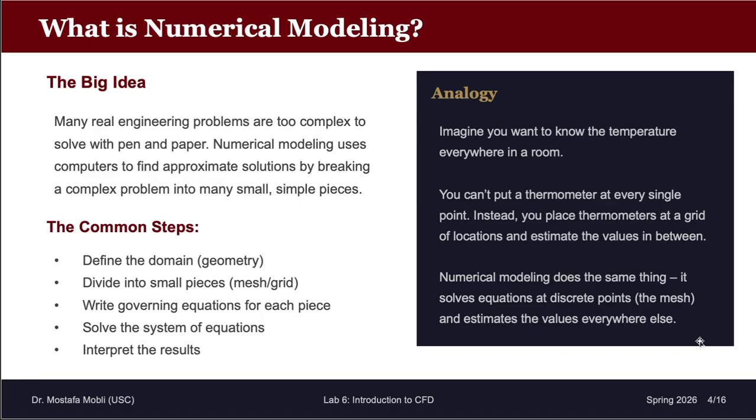The steps we always need to follow are: define a domain, divide our domain into smaller pieces, identify the governing equations, apply the correct governing equations for each piece, solve the system of equations, and then interpret the results.